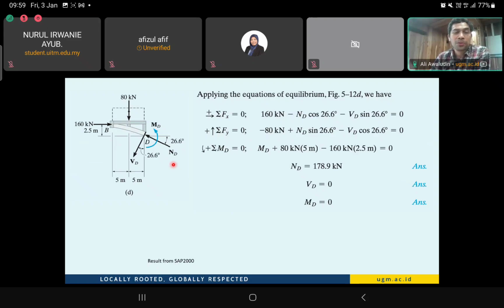This is the best way of utilizing it. For example, if you have a concrete arch system or maybe stone, long time ago our ancestors, as our history demonstrates, used stone for arch bridges, because stone has very high compressive strength but low tensile strength. That's why in this arch system we only have compression members. Using steel should also be okay, but you have to worry about buckling. Using concrete or stone is a good example because all parts of the arch system are in compression.